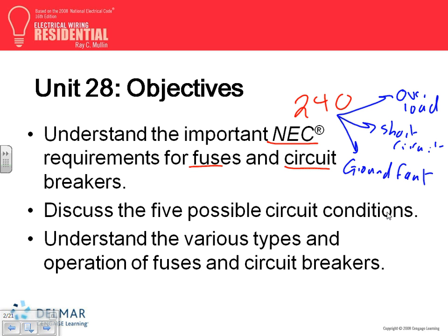And overload, we talked, guys, about overload. If you have a conductor that's rated for 15 amps, and you went and loaded that 15 amp conductor with 25 amps, that's an overload condition. Maybe 50% more, double, maybe triple. Short circuit: you have a three-phase circuit and you grab phase A, phase B, and phase C, and you bolt the three phases together. That's a short circuit. The impedance will be extremely small and the amount of current will be extremely high.